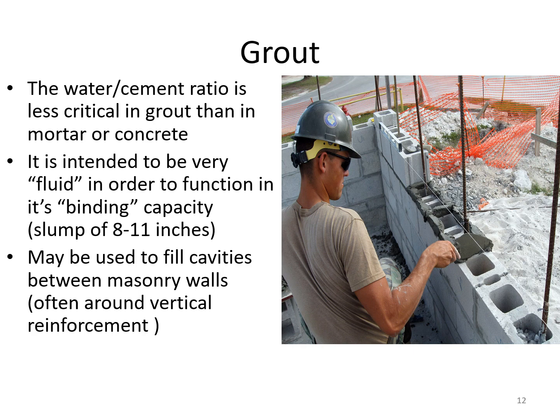They're now mostly stainless steel U-type bolts, and basically what you do is you place that right in the mortar that goes between the bricks, and when that all dries together, that allows connection to the wall, while still maintaining that void, which is a weep area for water and moisture to be able to pass between the brick and the wall surface where the moisture barrier is. Very important to have that.